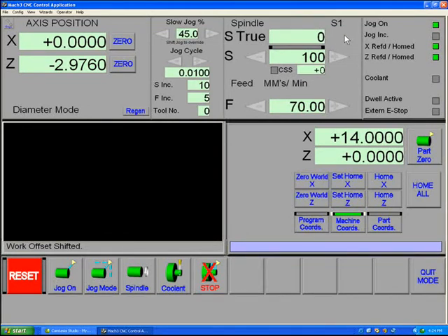This is often done with the Omron SB5V optical sensor with a piece of reflective tape. Some people have optical sensors that go through a single hole in a slotted wheel on their spindle. Either way you look at it, as long as you feed it 1 pulse per revolution, you'll get an accurate spindle speed reading. There are alternatives to that where you can feed up to 12 or 15 or 16 pulses per revolution, but we found through testing that really all that's required is a 1 pulse per revolution system.